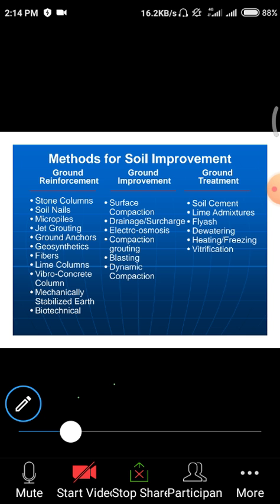There are different kinds of load: dead loads, live loads, and others. Dead load can't move, but due to the movement of live loads and external atmospheric parameters like wind, we face some stresses developed internally in the structure. Those stresses develop from one part to another, from top to bottom. They are transferred to the footing, and from the footing to the soil. If the stress distribution is proper, the structure will withstand for a long time.